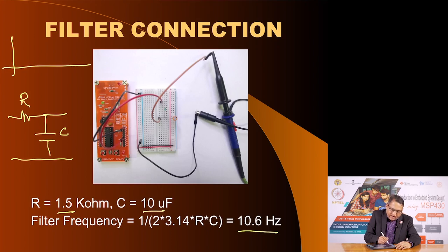Which means in my signal I have something like this. So, this 3 dB frequency is 10 hertz here, but my carrier frequency, that is the PWM carrier frequency, is 1 kilohertz. As you see, it is much higher, and the signal which is modulating this is much lower. As I mentioned, we estimate this signal to be 2 hertz. It is very well within the pass band of the low pass filter.